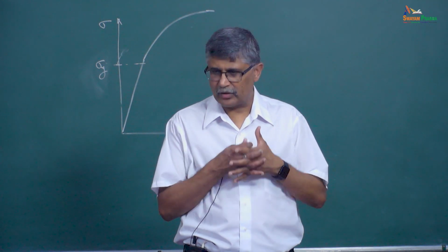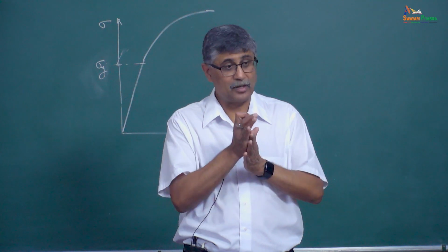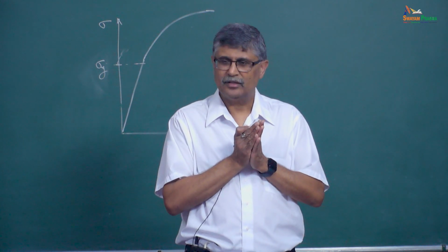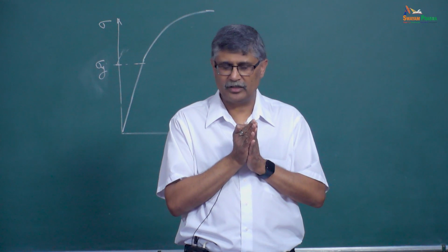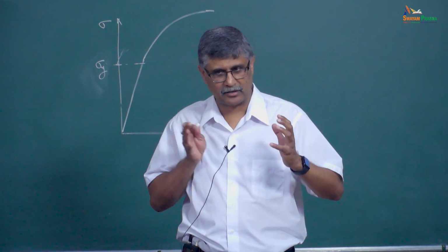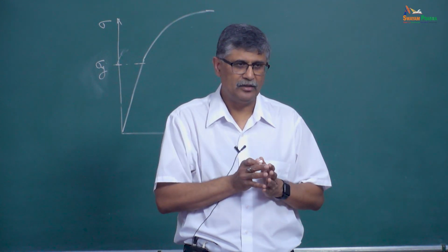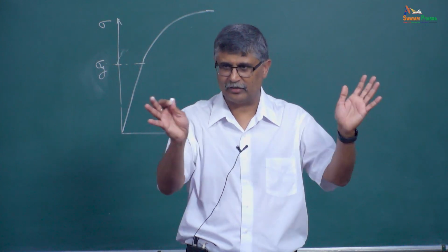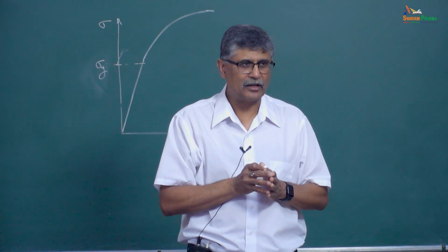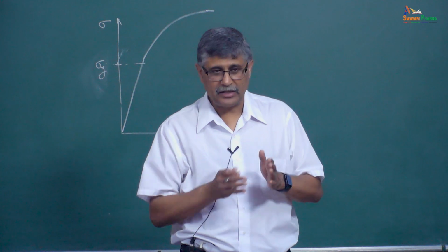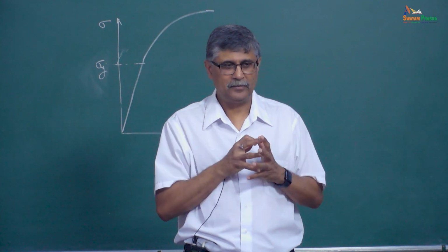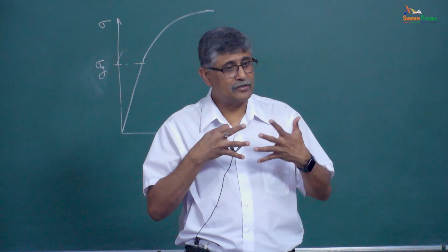So for these dislocations, there is the phenomenon of slip. When you apply shear loads, these dislocations move within the material. They accommodate the external deformation that you're imposing on it, right? Till they can no longer accommodate, when the thing fractures and fails, right? That's what happens.